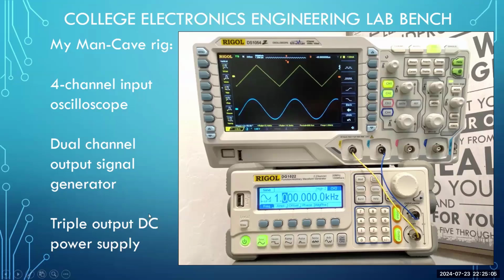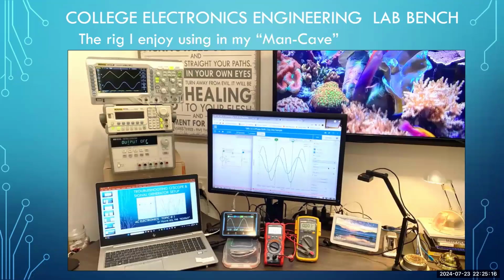And then what I had in the previous slide was a benchtop power supply. Now what you've been using are your little breadboard power supplies, but a benchtop power supply is quite a bit more stout. If you magnify the screen, you're going to see this is a triple output benchtop power supply. I've got a fixed 5 volts, and a variable 0 to 25 positive, 0 to 25 negative, and this thing is built like a brick, more like a concrete cinder block. It's about the weight of a concrete cinder block. So guaranteed it's going to have quite a bit more substance than the breadboard power supply that you're using.